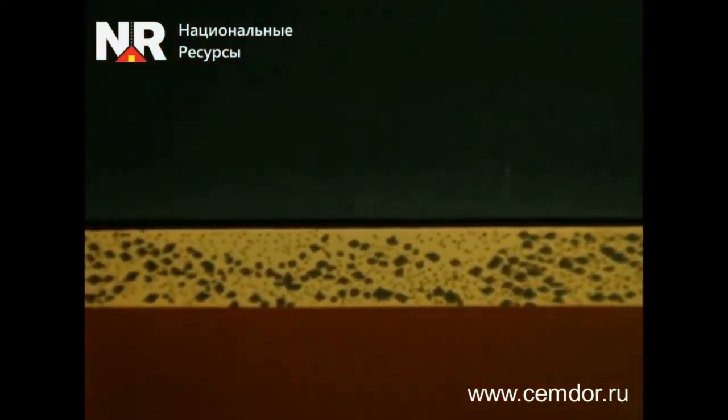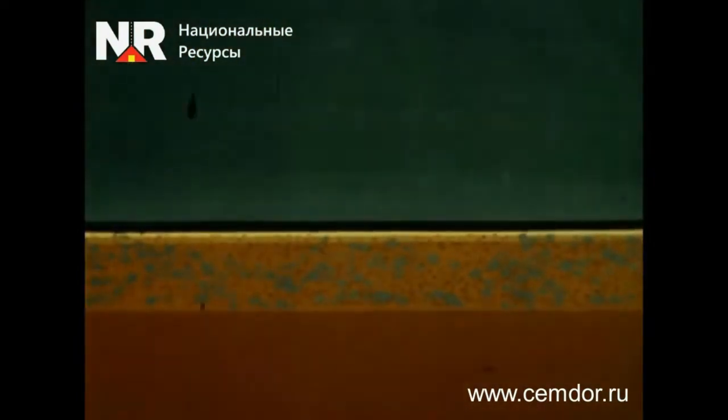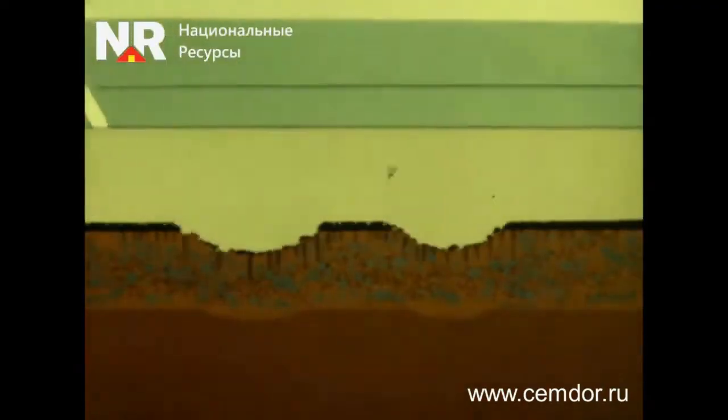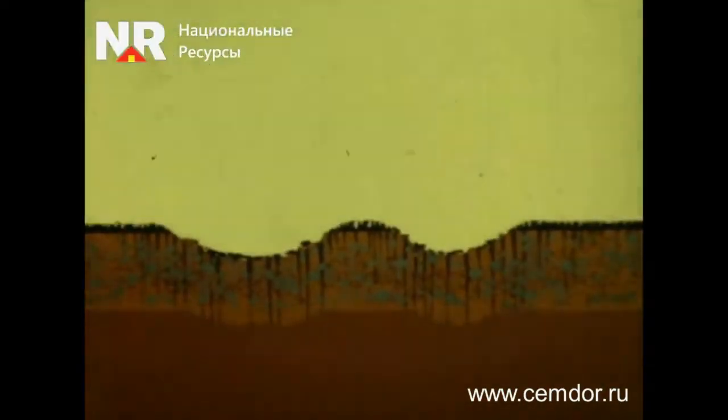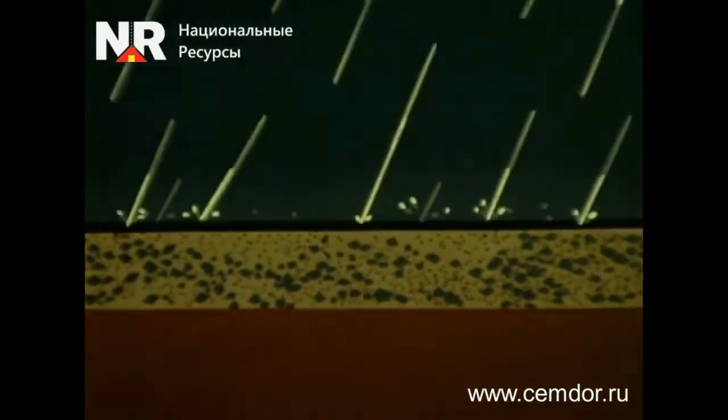In dry conditions, well-compacted soil can already be used as a road structure. However, moisture penetrates most soils, causing a loss of stability. Under the influence of loads, the road surface deforms and tends to deteriorate. In other words, the soil becomes plastic and loses its strength. This problem can be solved by adding cement to the soil composition. It binds all the soil particles into a monolith, giving the material structural strength. Moisture penetration into the soil cement structural layer is minimal and it retains its strength and stability under any conditions.